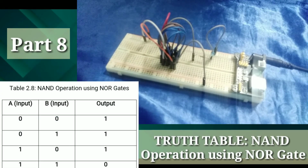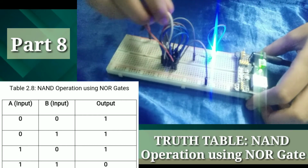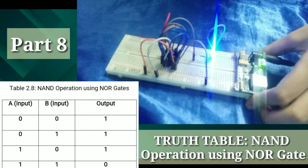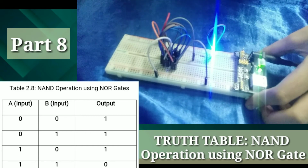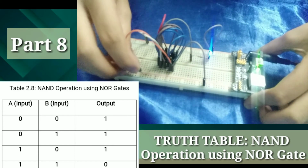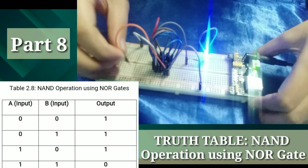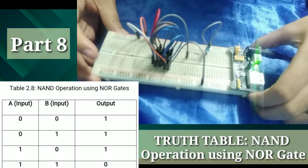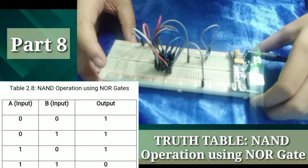Now, for our truth table for the last part, again, for A is 0 and B is 0, the LED has been turned on. If A is 0 and B is 1, the LED is still turned on. If we interchange the inputs, so our B will be 0, again, the LED is turned on. And lastly, if both of the inputs are 1, contradictingly, the LED is turned off. So that's for our last circuit experiment.